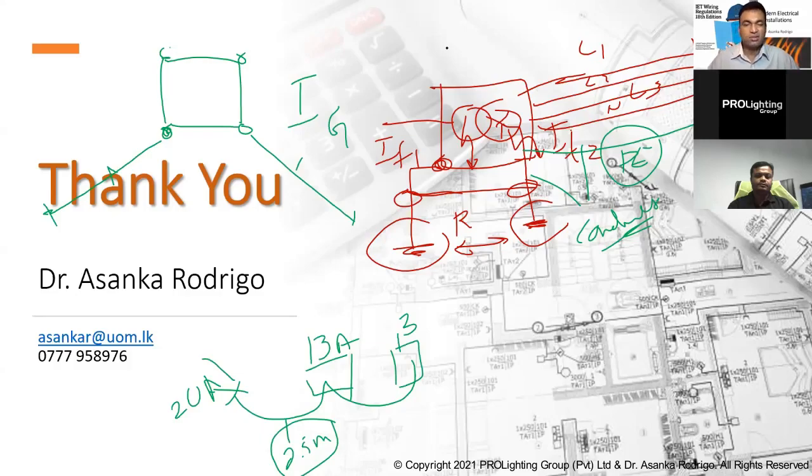Because insulation monitoring is also considered a way of residual current monitoring, but the only thing is there should be automatic disconnection. What the insulation monitoring devices do is continuously monitor your insulation level and detect whether there is a drop in the insulation level. If there is a drop, it will give an alarm so that you can react first. But if the insulation level keeps dropping, that can create harm if somebody touches your system, and then that can create a hazardous situation.